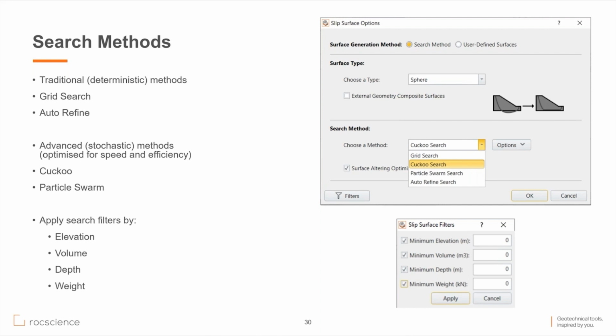in the survey software. From experience, MapTech has a simplification tool. Rocscience software also has a simplification tool when you import, but if you can bring a smaller file into the program initially, it's going to be faster to import. So it all depends on the level of detail that you are required to retain.